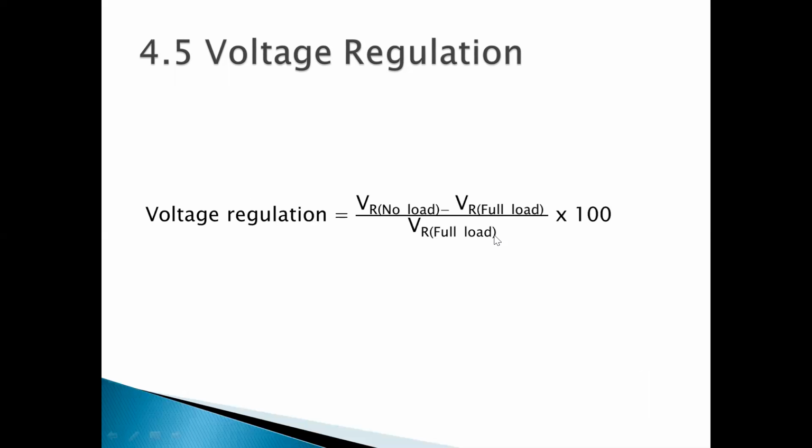We know that the full load voltage will be less. For example, at no load my voltage is 100 volts, and at full load the voltage is 90 volts. So 100 minus 90, divided by 90. It just tells the percentage of voltage regulation, nothing else. So it's a formula, you have to remember this.